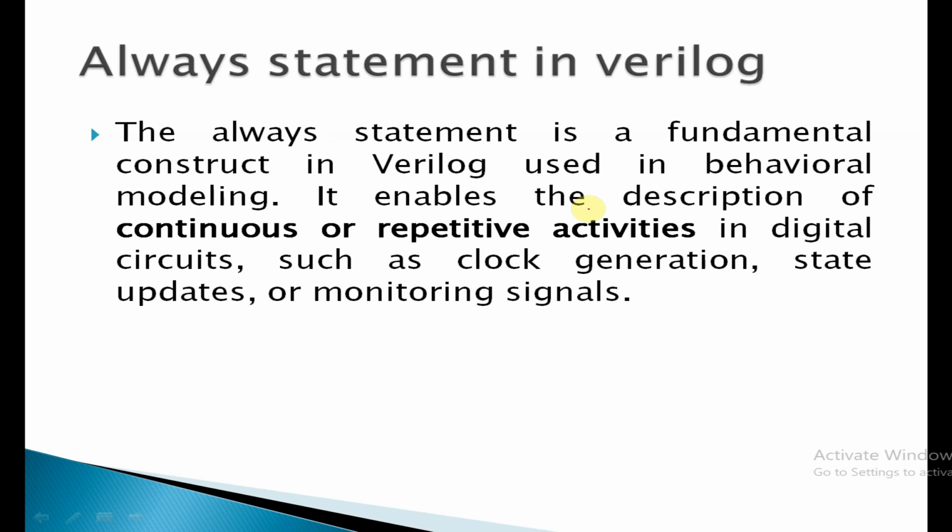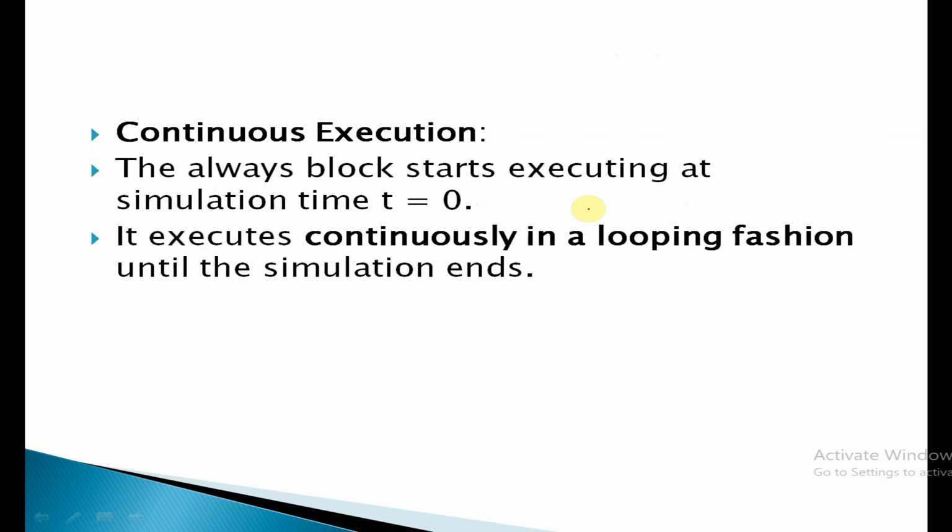We can use it for clock generation, state updates or monitoring signals. The always block starts executing at simulation time t is equal to 0, like the initial block, and it will execute continuously in a looping fashion.